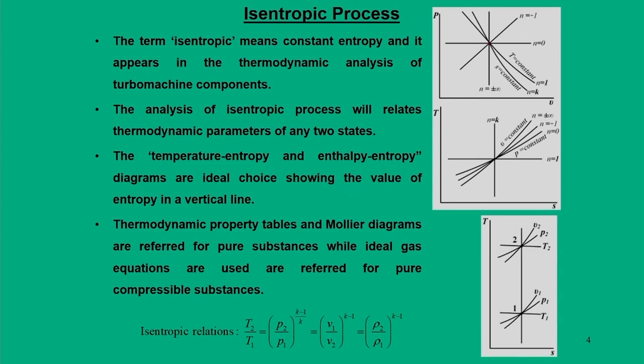We have already discussed the term isentropic, which means entropy is a constant parameter when the system undergoes a change of state, and this isentropic word is very vital in the thermodynamic analysis of turbo machine components. In fact, it relates the thermodynamic parameters between two states.